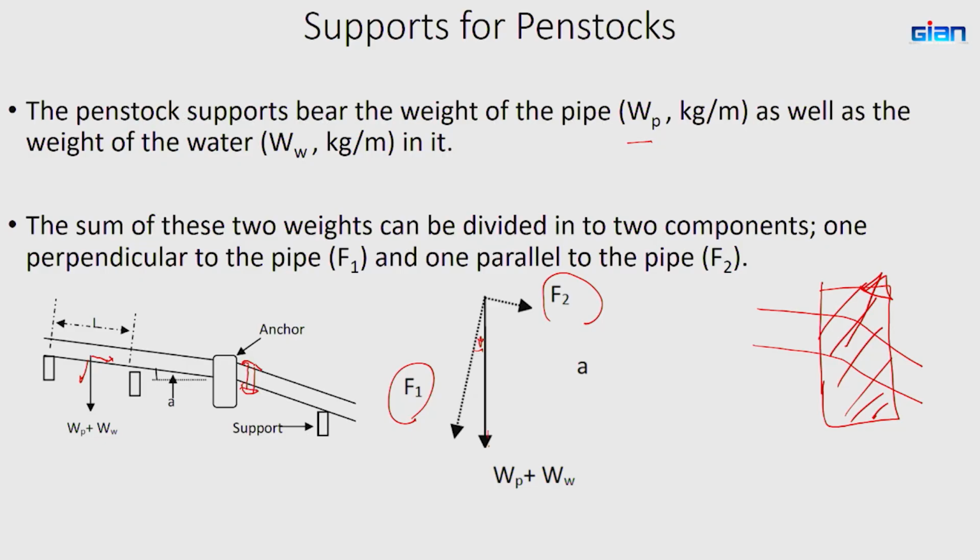Then if you are holding at 2 places rigidly, the pipe can warp, bend. Therefore, you must have an expansion joint. Expansion joints are normally kept just below the anchor here. An expansion joint will have a cut here, and a covering arrangement here with bolts and all that.